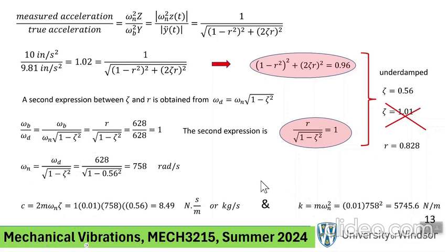There we are. So here's what happened. We had a measuring device. We knew two things about it. We know its mass, and we know its damped natural frequency. Of course, that damped natural frequency can be coming from recording the data over a free vibration and finding the damped period. They'll give you the damped frequency. So we had the mass and the damped frequency. That's number one. Then we used it to find the oscillation frequency of a vibrating wing. And we came up with 10 meters per second squared.